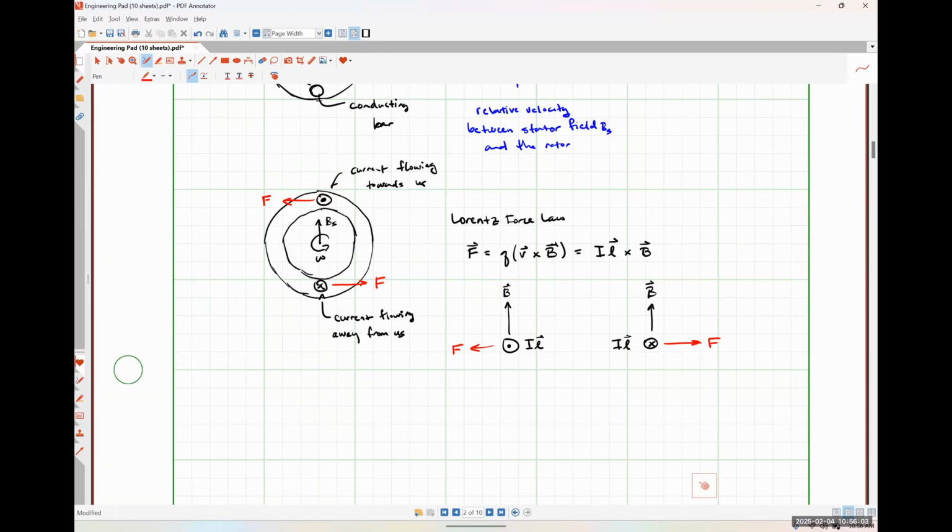This is why we get a spinning rotor, because we have two forces that are effectively generating a torque, right? Torque is just force times distance. So we have these two forces that are pulling. One is pulling the top to the left, the other one is pulling the bottom to the right, but they're affixed on a rotating pin. So this is just going to cause this guy to start spinning. So we're going to see that our rotor is going to follow the direction of omega, okay?